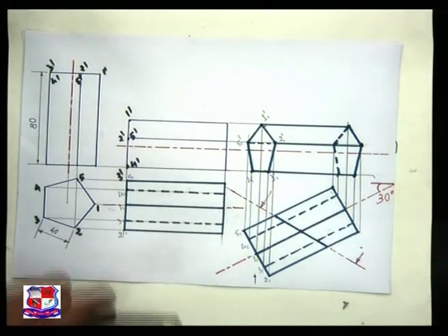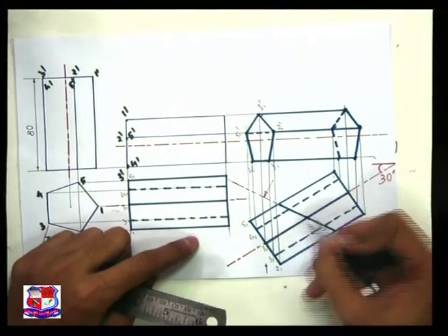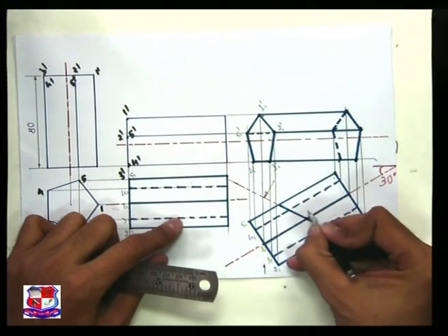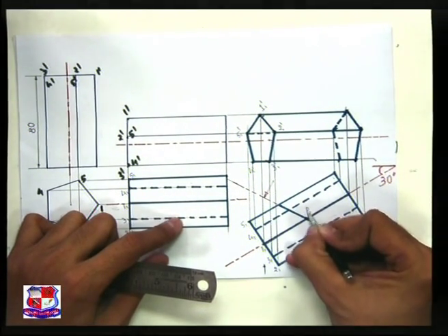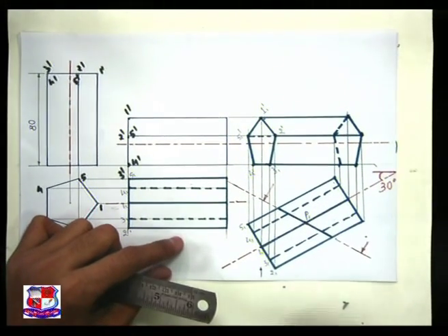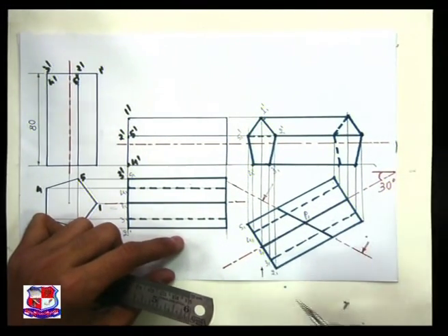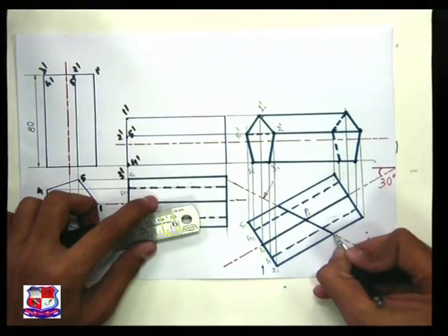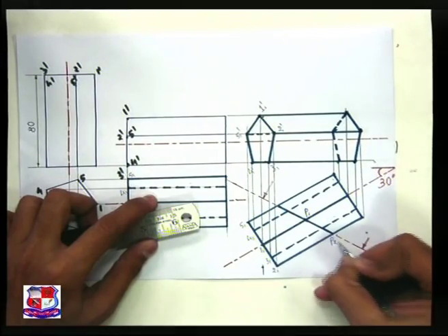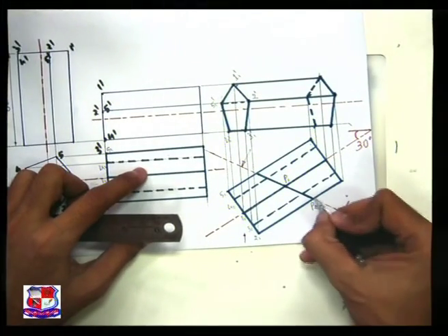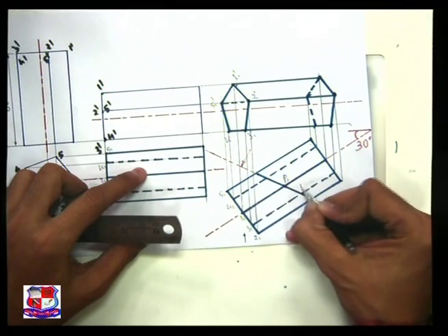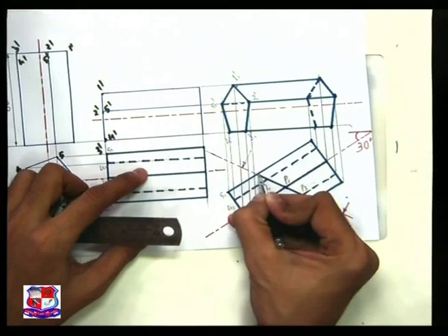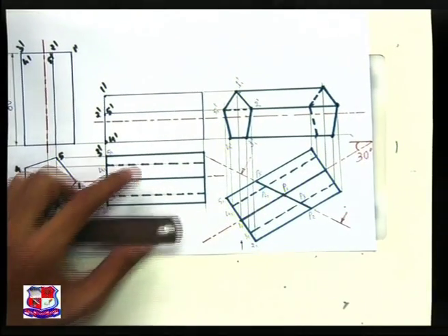Now find out the points of intersection from this top view and cutting plane. So first is 1 dash here, so let me locate point P1 over here, right? Intersection of this cutting plane and the horizontal line from point 1, line from point 2, here point number P2 would be there, line from point 2 and cutting plane is here. Here is point number P3, here is point number P4, and here is point number P5.